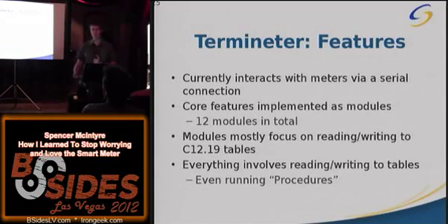If you want to modify, of course, you're going to have to write to one. If you want to retrieve it, you're going to read from one. But even getting the meter to do things, running procedures, is a series of reading and writing to tables. There is a special table called the procedure init table, which is in the general config decade. When you want to have the meter do something like update the ID, you write information to the procedure init table and you read the responses back from the procedure response table.